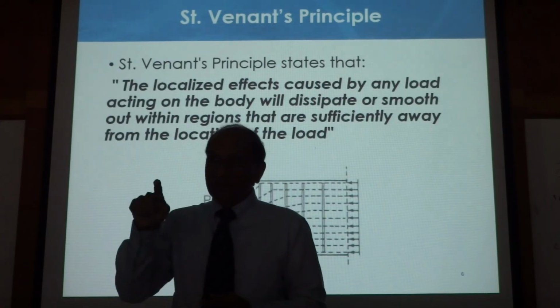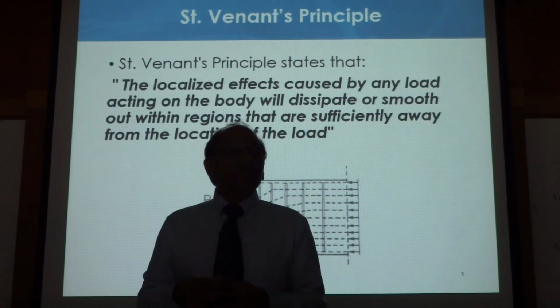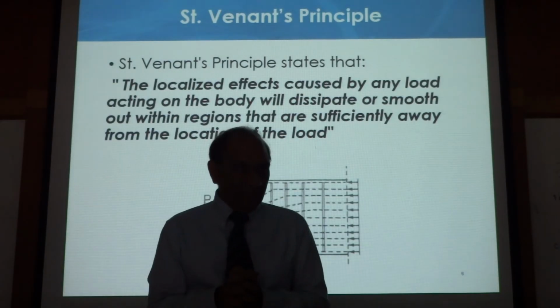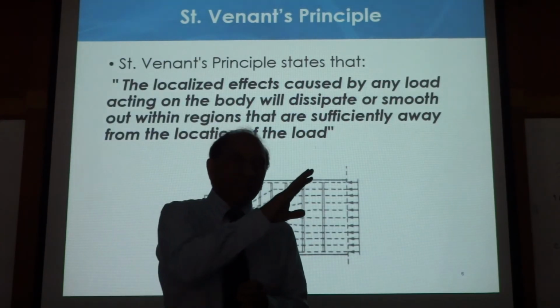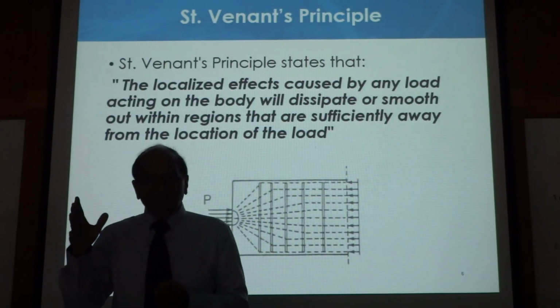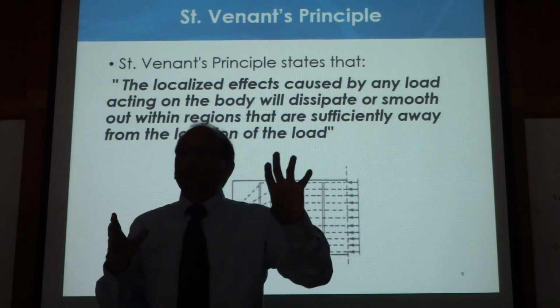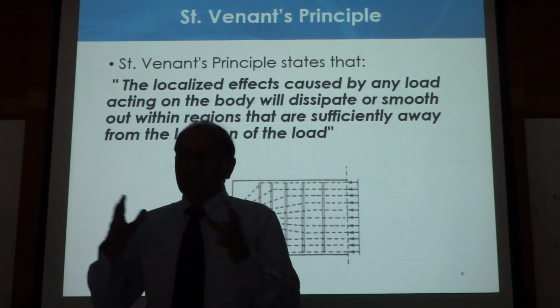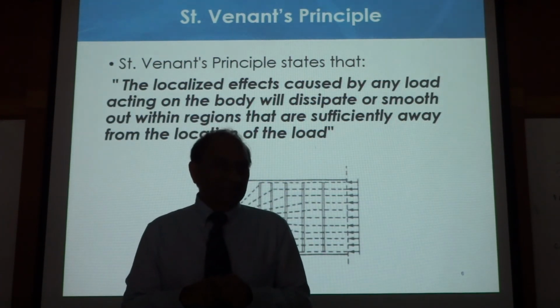They have a local effect, and after some time, they disappear gradually. So this is very interesting for us: even though in some beams plane sections do not remain plane, those places where they do not remain plane are only localized, not all the way, right? Because that's what this is saying.